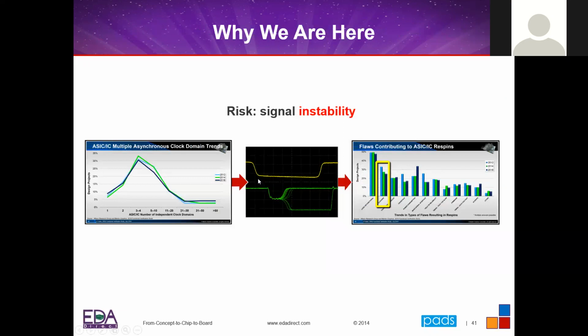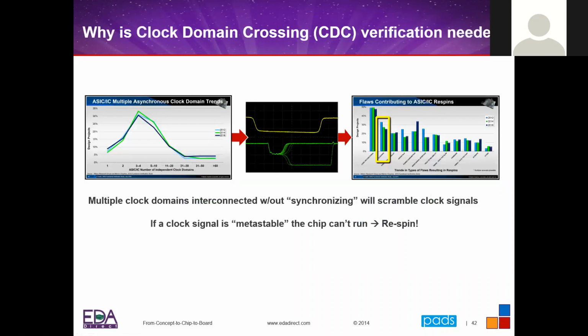What we're talking about is basically setup and hold violations. So if the clock is coming along and the data changes too close to the clock, what we'll see is the output will kind of go metastable for a while and ring, and then it'll either go to 1 or it'll go to 0, and it's unpredictable what it will do. And it might even ring forever.